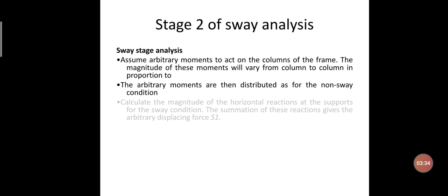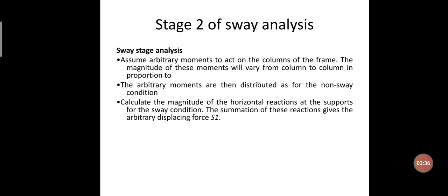The third step is that we need to calculate the magnitude of the horizontal reactions at the supports for the sway condition, and the summation of these reactions will give rise to the arbitrary displacing force. That displacing force is taken to be S1.